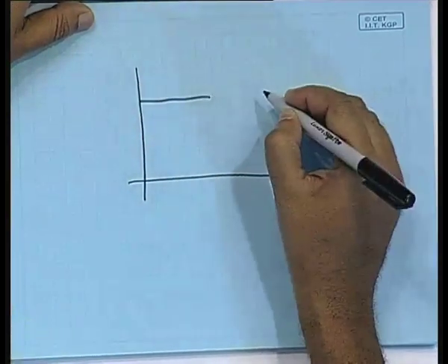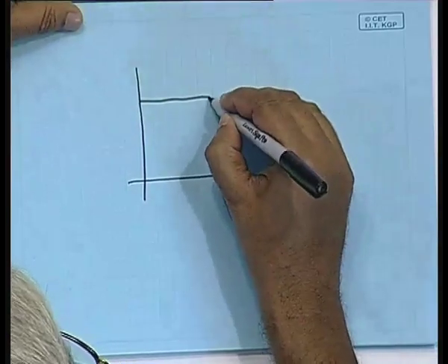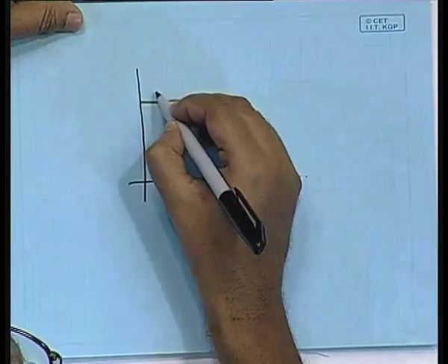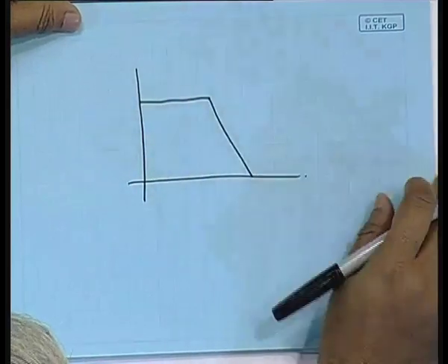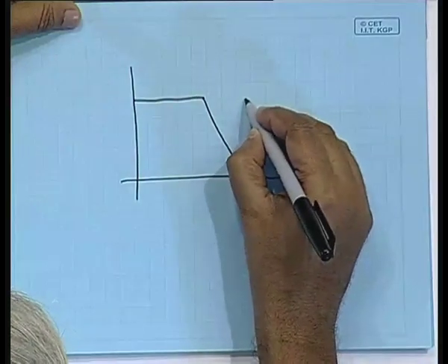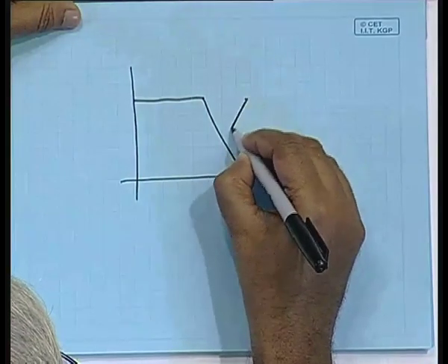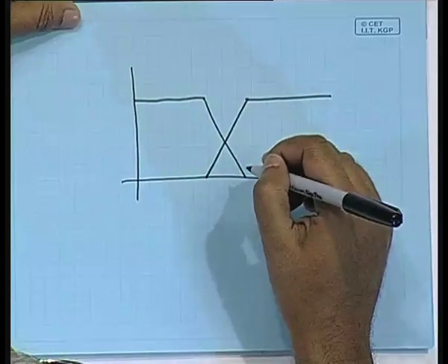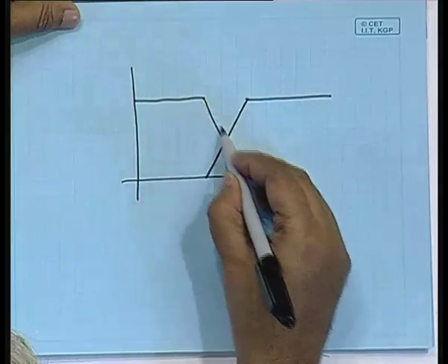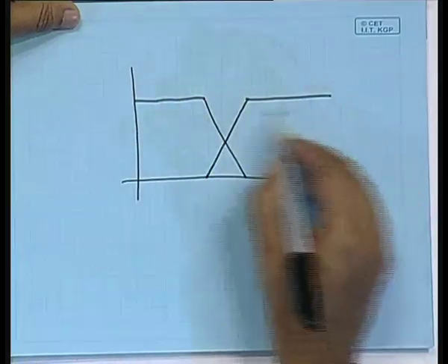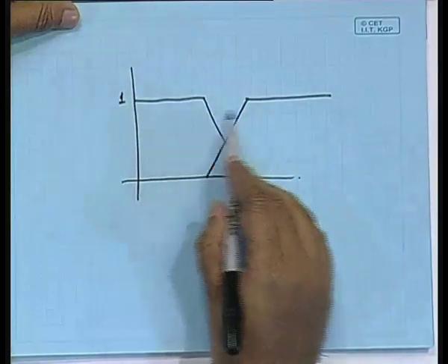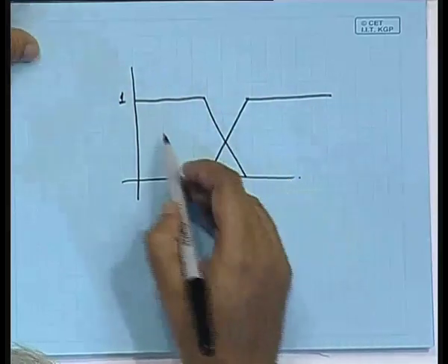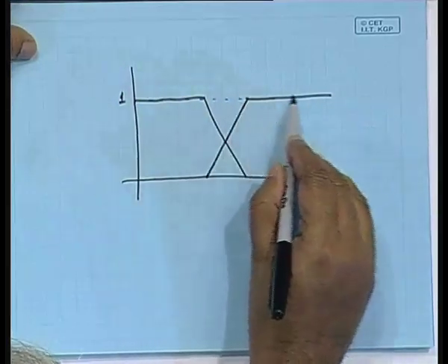Now, I cannot have an ideal filter, that is not practically realizable. So, if my LPF, the low pass filter, is like this, and I am able to construct the high pass filter such that this becomes my high pass filter, then the overall filter characteristic should be, if this is equal to 1, able to pass all the frequencies. Together the overall response should be this.